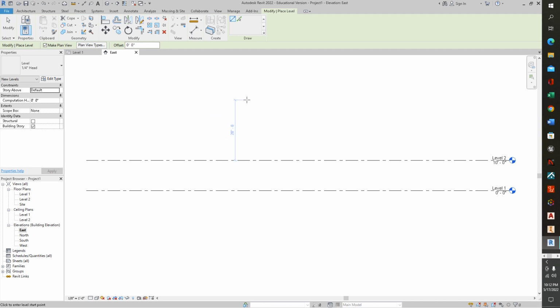Maybe we do want to change that later, but we'll go up here to pick lines. It's in your draw menu in the ribbon, at the end of the ribbon. You have lines and then pick lines. For this, because they've got it at 10 feet, we'll carry on with having our offset being 10 feet. It should give us plenty of space on there. Same as how we did it if you followed any of the commercial building stuff.